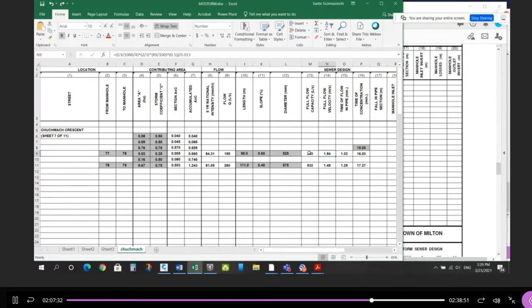So here's how you calculate V. Here's how you calculate Q. And again, it's the formulas that we showed before, Manning's equation. This one here, you'll see the exponent 2/3, the exponent of a half, divide by n, 0.013. Okay, so it's all there. And then this is the capacity, which has the end area. Here's pi. Remember pi? Pi bracket bracket. That's how you get pi.